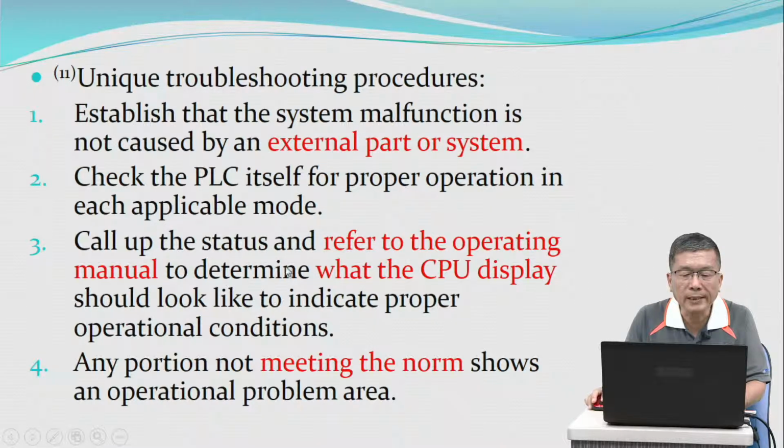Call up the status and refer to the operating manual to determine what the CPU display should look like to indicate proper operational conditions. An indication not meeting the norm shows an operational problem area.